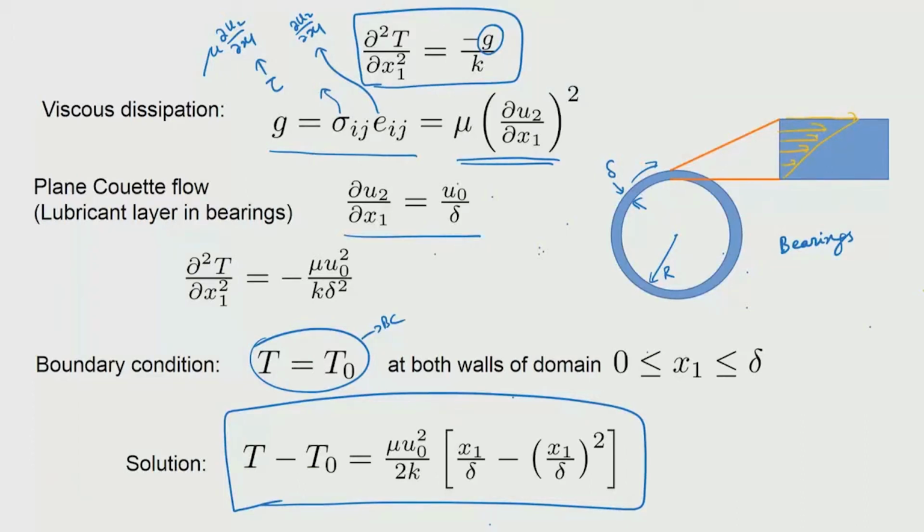So, clearly there is a gradient, and that gradient is what is causing the viscous dissipation, which is causing the heating. Now, the temperature variation is across this distance, and you can see it is parabolic. Which naturally means that you would have the maximum heat at the center, and therefore, if this was a velocity profile, then the temperature profile would have something of that nature. Okay. Now, the maximum heat that is actually obtained here, in this delta, is the reason why, for example, what is in this region is getting hot.